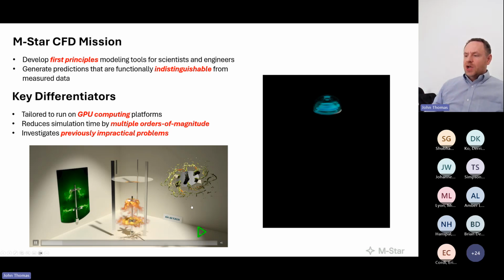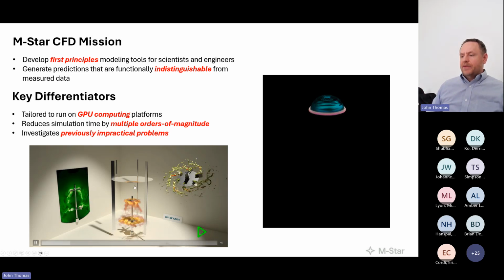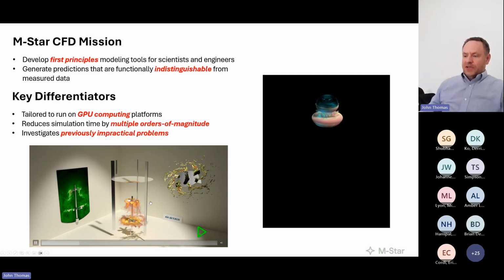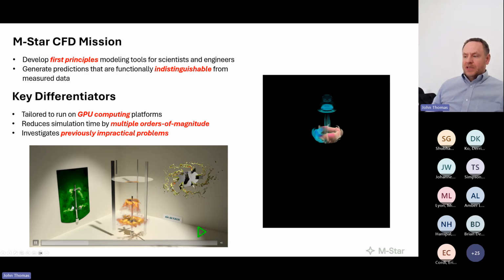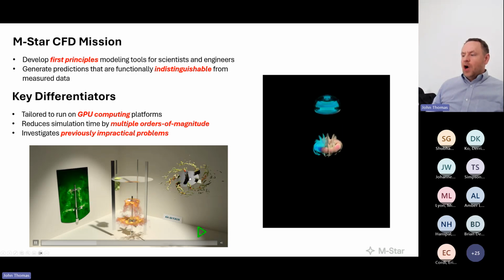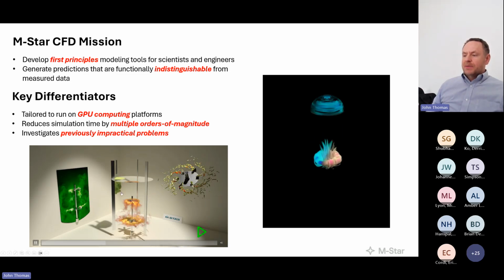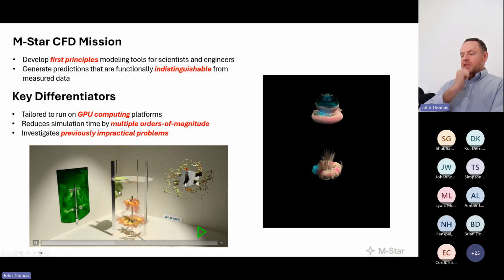Here we have a process where we're adding some sort of secondary fluid to this agitated vessel. There's the free surface. Here we're cutting a plane through to look at the velocity. Here are some of the EDR and the trailing vortex, as it were. Here's the blending of that dye as it moves throughout the vessel.